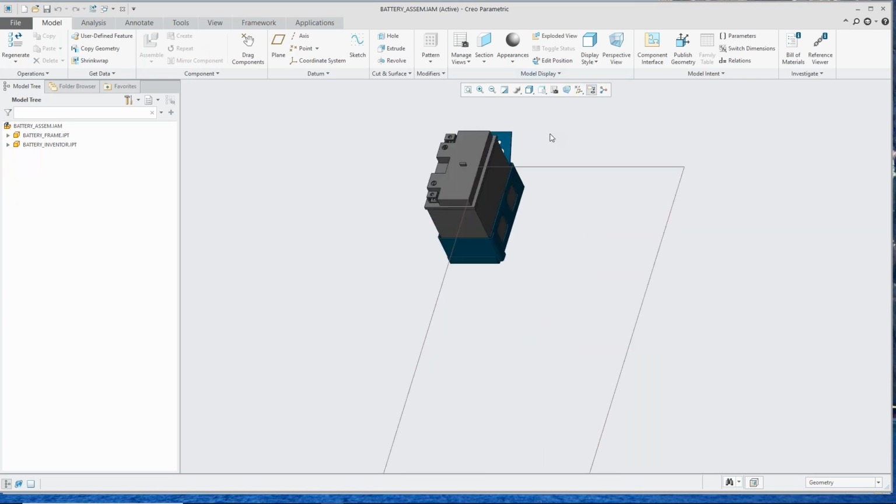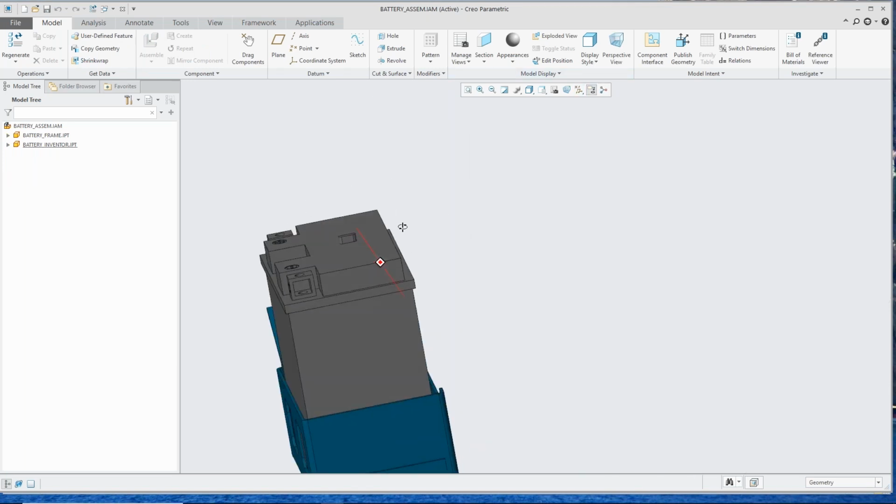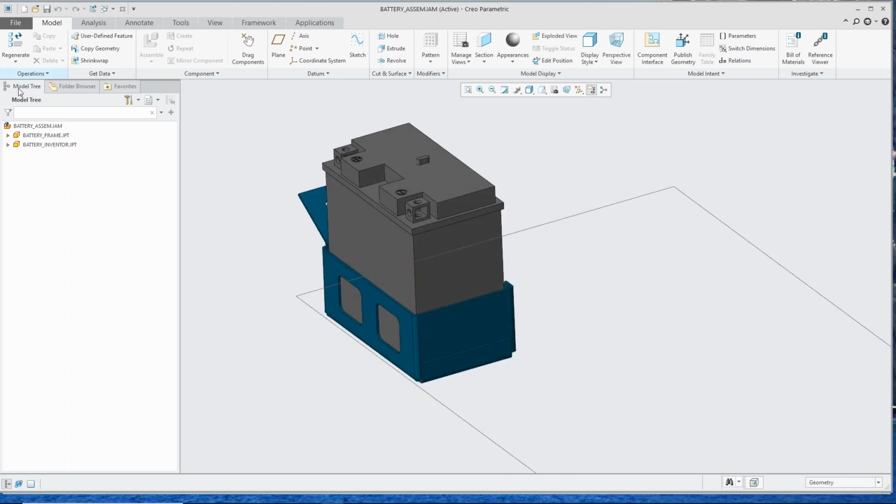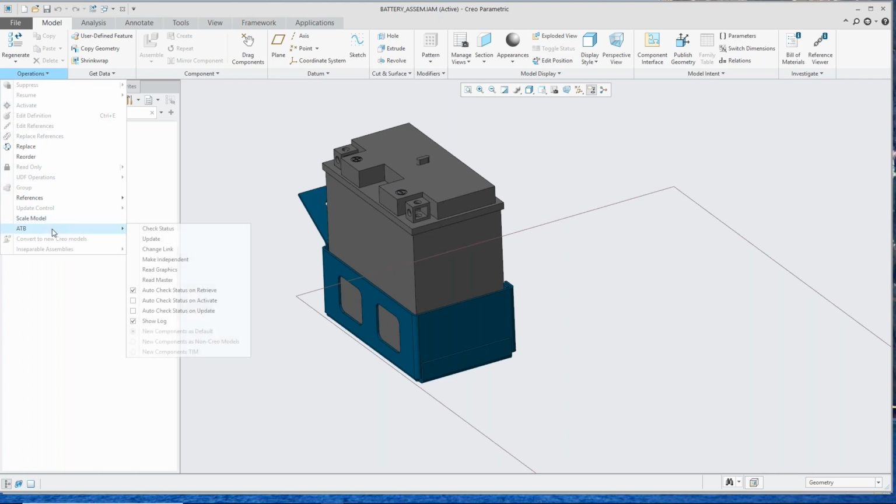So let's go and take a look back at our, oh, sheet metal is one other thing I just wanted to touch on. So let me call up a sheet metal part. Let's just make one. I'll say okay. So here's our sheet metal part. I'm going to grab a couple edges here just so we can highlight some new things. I'm going to pick these two edges and extrude those out.